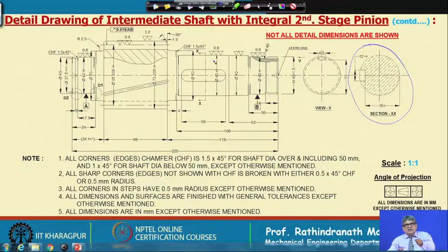While you are machining, if it is a CNC machine or somewhat, if there is a good measuring device, you can measure during the cutting process, but ultimately you have to measure these dimensions. This is nothing but the depth of cut mentioned there, subtracted from the diameter there, and obviously there will be some tolerances. Of course, on the shaft you have to give some tolerances, that you have to calculate or consider from the specification, and that you have to give.